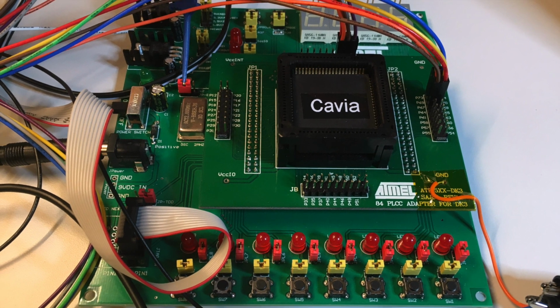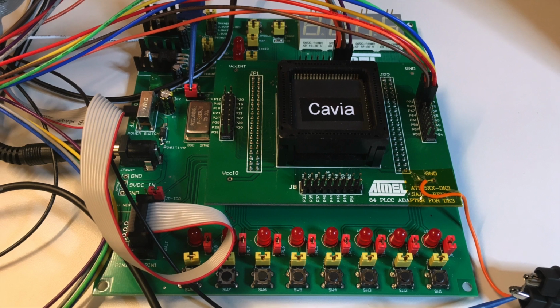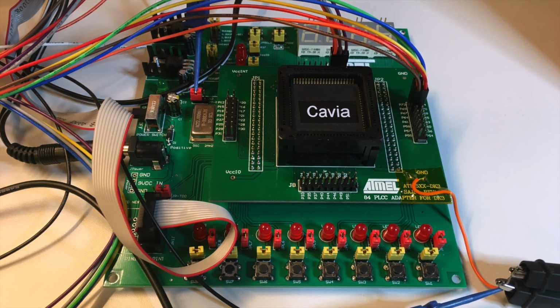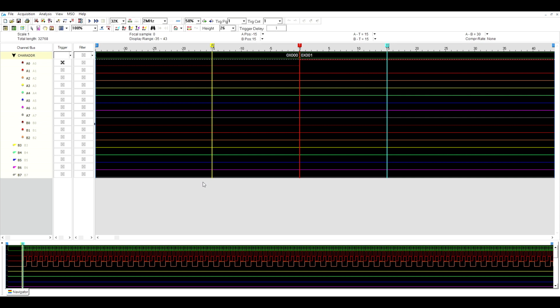So now we change the wire harness again to capture a different bus, this time the character memory address bus. Okay, this is the same thing, but now we are looking at the address for the character memory, not the video memory. We still have those 11 bits. These are just the logic analyzer probe identifiers, but basically these are the 11 bits of the character memory address, which is basically an indexed version of the address of the first byte of the character that we receive from video memory as an output of the video memory.